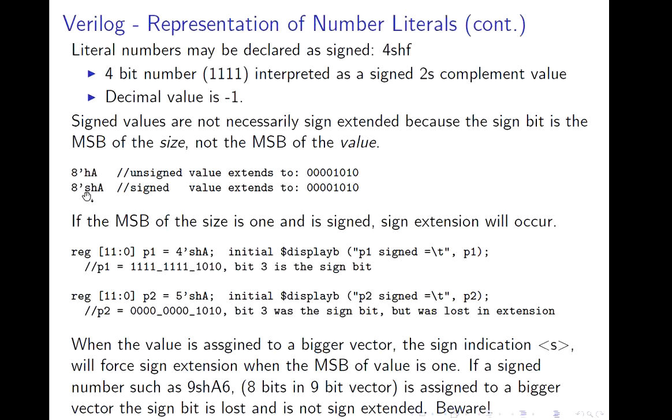But when it comes to a signed number, the MSB represents the sign. Now that sign value should be considered only when you append the values and make it an 8-bit, because here you have mentioned 8-bit. So the number A is 1010. Now don't consider the MSB of A as 1 and call it a negative number just because it has a value of 1 for the MSB. Because you remember, negative numbers are represented with an MSB value of 1, and positive numbers with an MSB of 0.